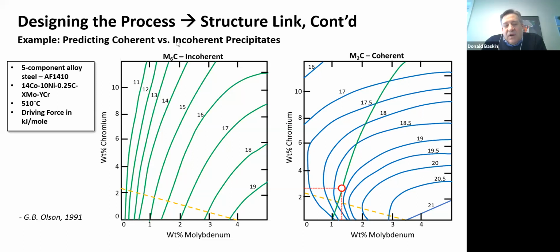Regardless, the Reynolds company in England has done a lot for bicycle steel. They've come up with some very interesting alloys, very similar to this AF1410, the maraging steels that strengthen by being martensitic and also by having precipitation hardening. They've formed a stainless steel version of that, so you don't have to paint your steel frame anymore. I'll probably talk a little bit about that later in the lecture.